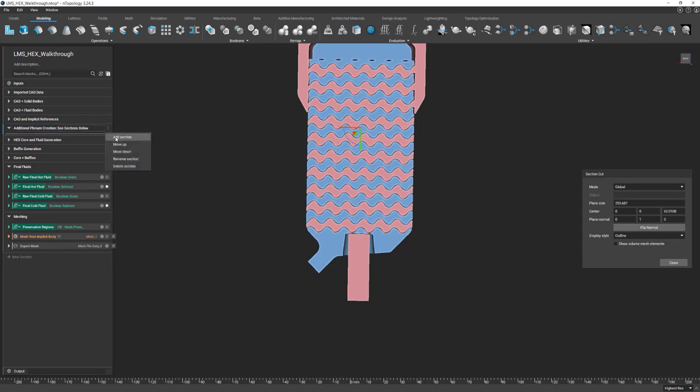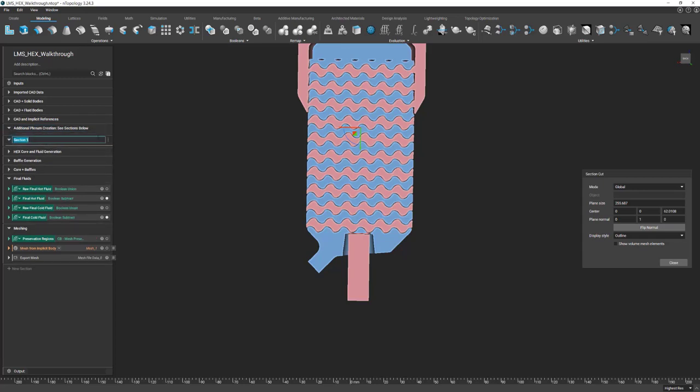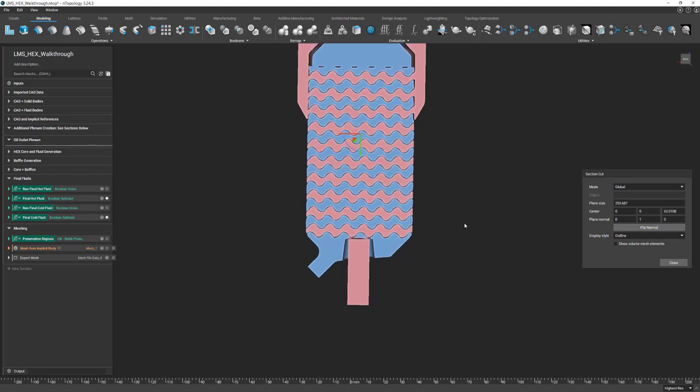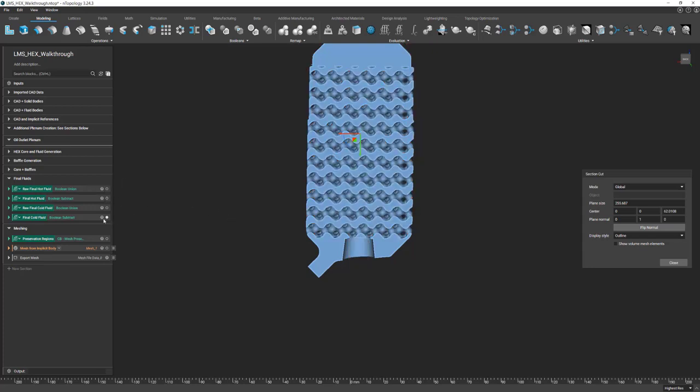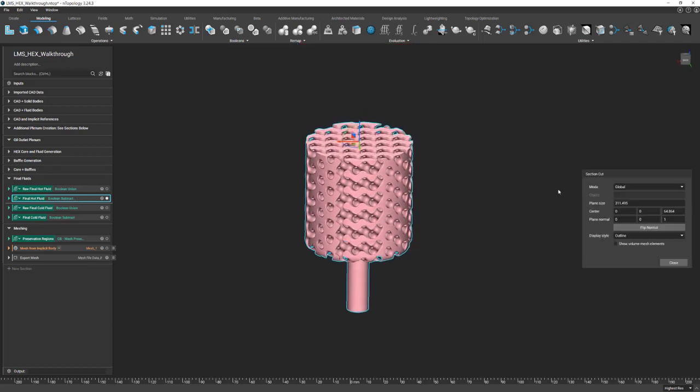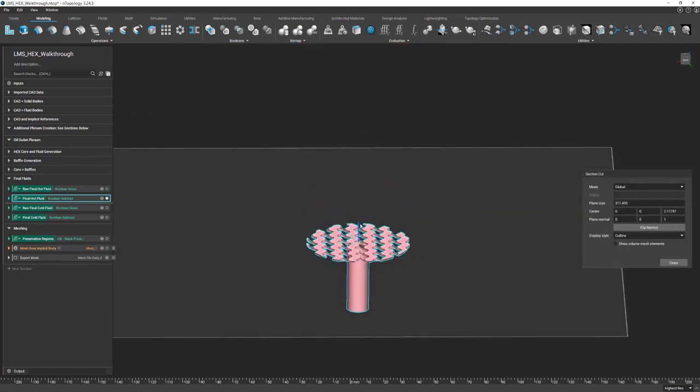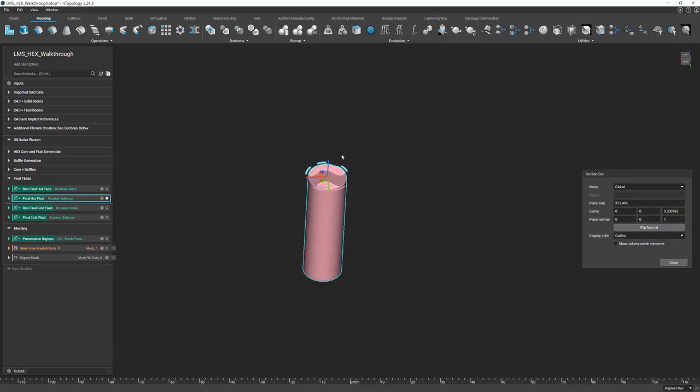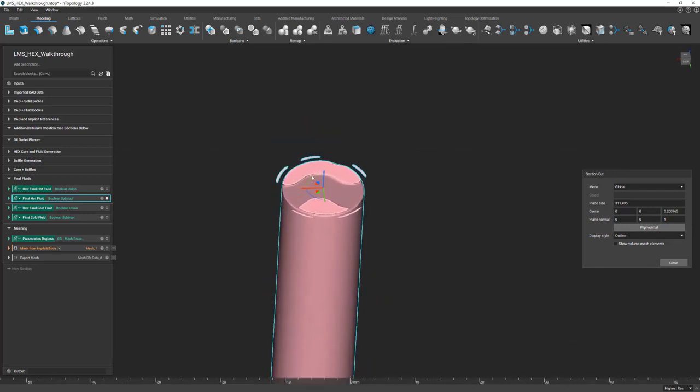So I'll create one more, add section, and I'll call this oil outlet plenum. At this point, I've already conceptualized the shape of the plenum that I want to create. If we look closely at the cross-section of just this fluid domain here, as we come into this exit, we'll see that all of the oil is really only exiting through these two passageways out of the hex core.